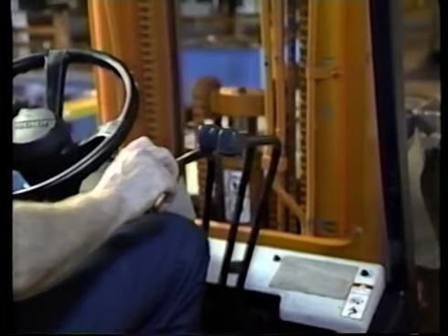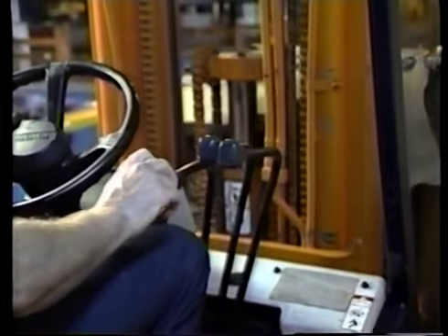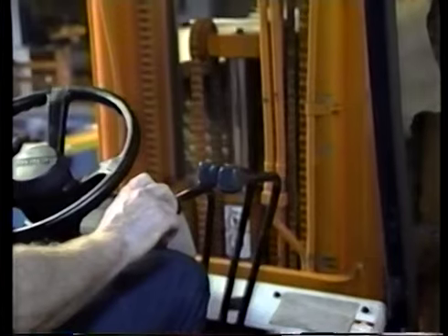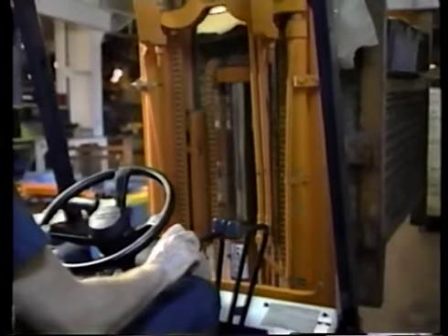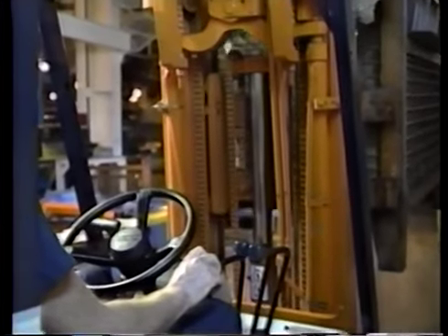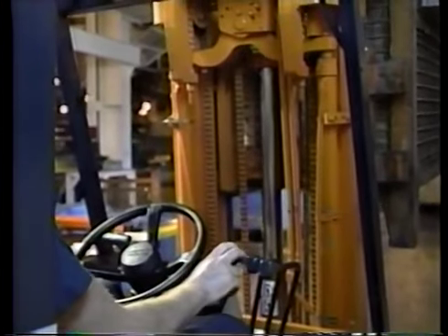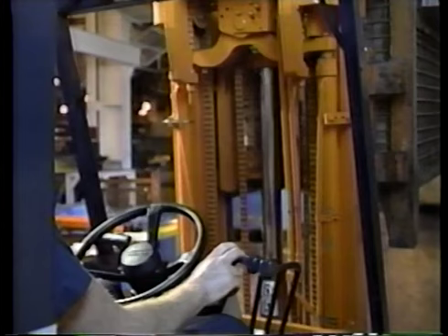When the operator shifts the lever, it moves the spool of a directional control valve in the lift's hydraulic system, raising or lowering the forks. When the operator leaves the shift lever in one position, even in the closed position, a relief valve prevents the continuing pressure from damaging the system by directing fluid back to tank.